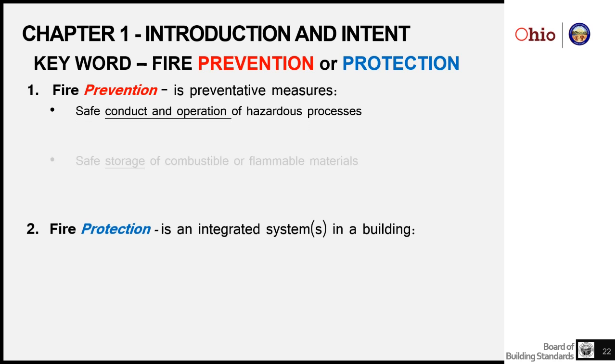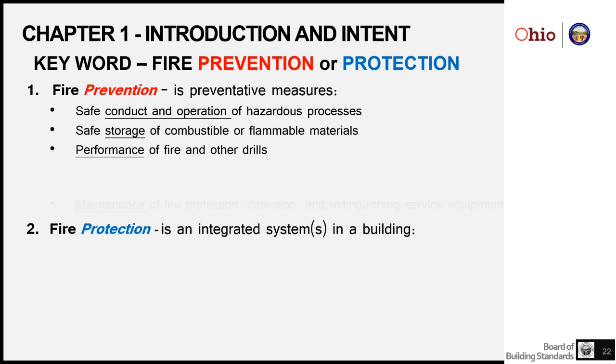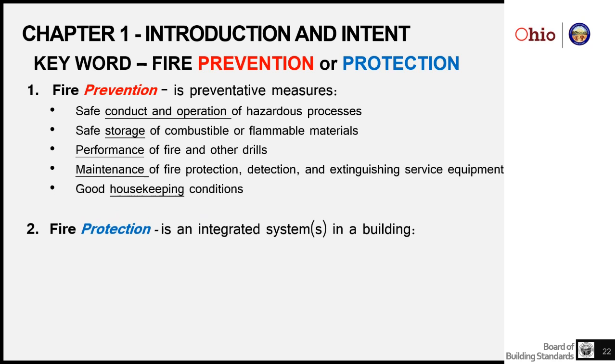So fire prevention is going to be talking about the safe conduct and operation of hazardous processes, the safe storage of combustible and flammable materials, the performance of fire and other drills, the maintenance of fire protection, detection and extinguishing equipment, and good housekeeping. So most of fire prevention is about what the owner is doing as they occupy the building to help keep all of those fire protection systems in good working order and keep their building and building occupants safe in terms of the operation of the activities that go on in that building.